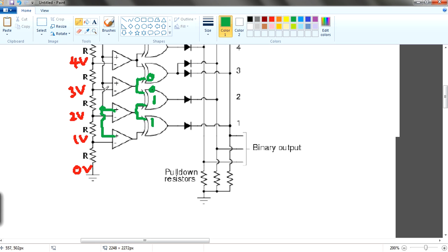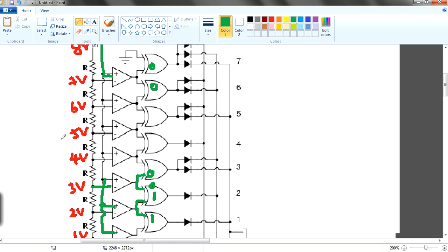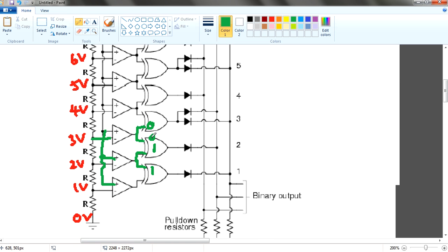This is 0 also. If you were to remember, the red color one is the referencing voltage, right? So your input voltage is 2 volt, which is lesser than your referencing voltage. So this is why it's 0 over here, 0 over here. And up till here, the input voltage is now the same as the referencing voltage. So you have a 1 over here. So therefore you have a 1, and then you have this portion over here. It goes in. You have a 1 over here binary. So my fault. Okay, this shouldn't be at this point 2, and if it's 2 volt, it cannot be the same.